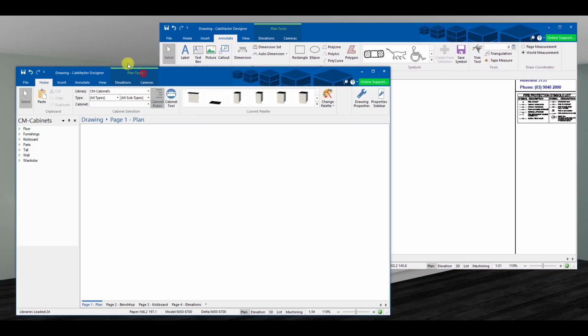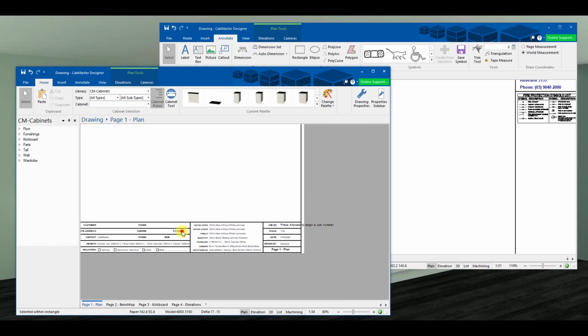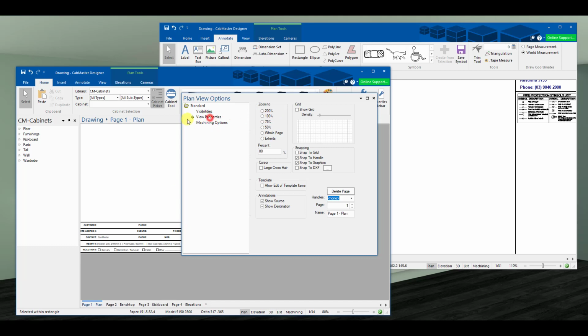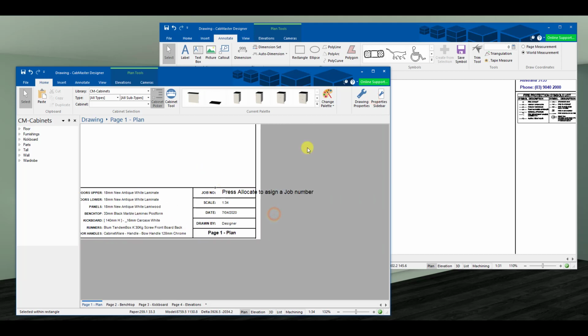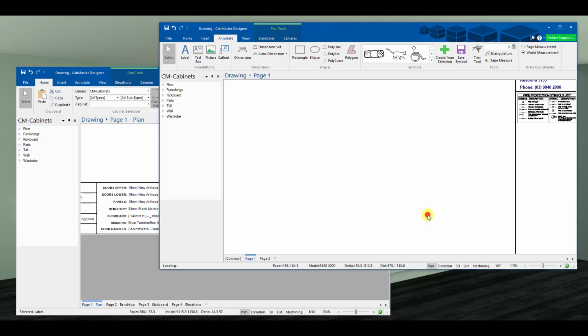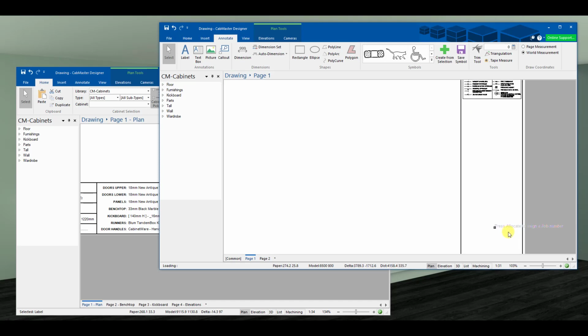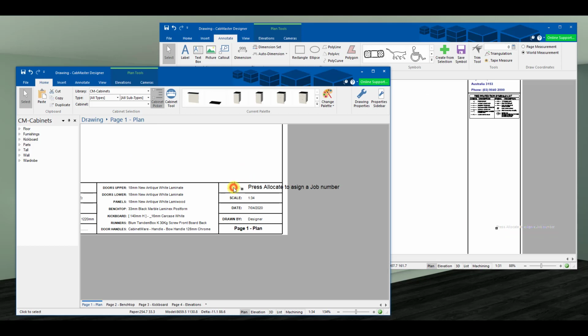So what we can do is go to the existing template on this version. I need to right click, options, and I need to view properties and go allow edit of template items. So we can do that because now these will actually be all active. Currently we haven't saved the template, so these are not active as template items yet. But if I want to get, say, this one here, I can actually go copy, come back into this one and go paste. And that will now paste that variable. So there's actually a variable behind that that comes on when you choose a job number.